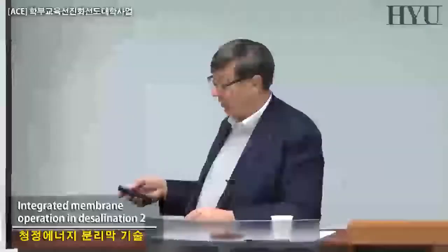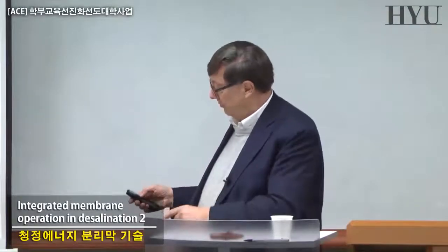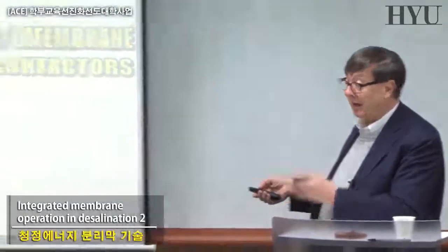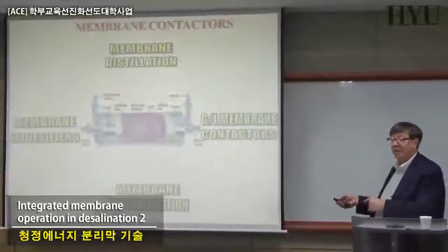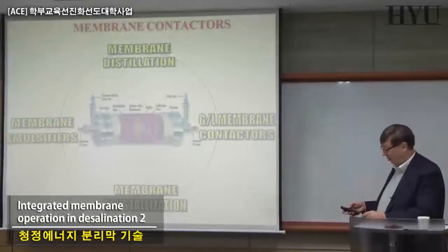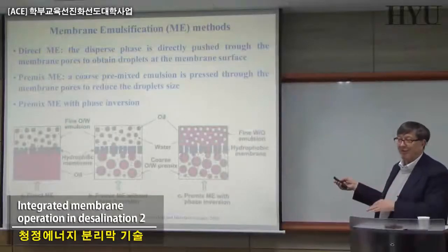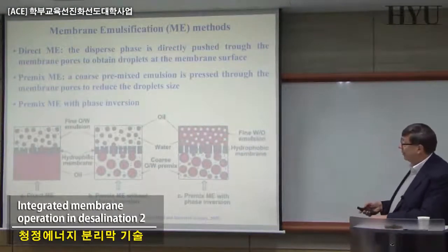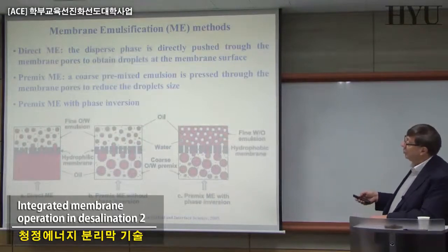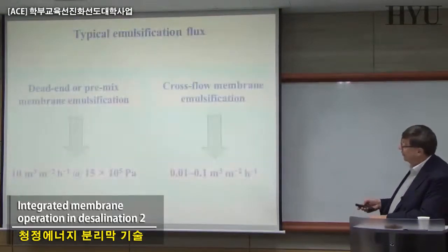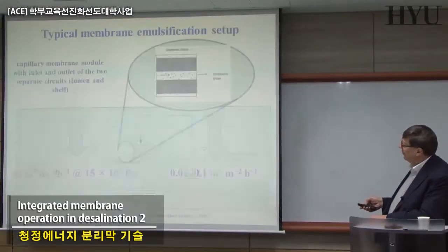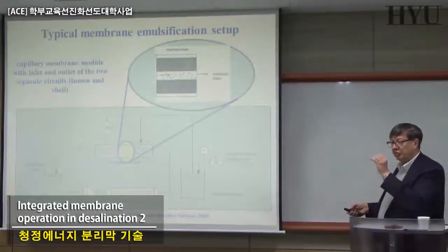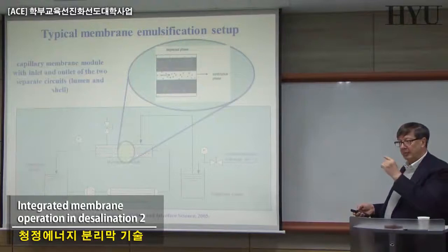They work on membrane emulsification. Because same story, that can be a membrane emulsifier, exactly as a membrane dryer, exactly as a membrane crystallizer, or a membrane distillation. Not exactly so, by the way, but not too different. And you can just try to produce your emulsion. You know what an emulsion is. And what is important, what you want to have with a cross-flow membrane emulsification system, is to produce homogeneous monodispersed droplets. Something similar we have been discussing, remember, in the crystallization.